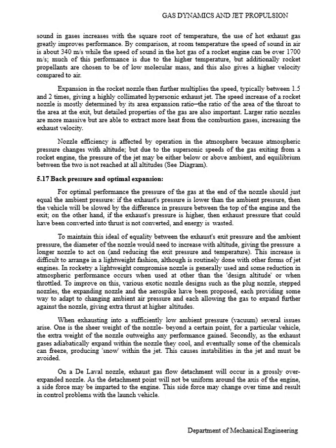To improve on this, various exotic nozzle designs such as the pulse nozzle, stepped nozzle, expanding nozzle, and the aerospike have been proposed, each providing some way to adapt to changing ambient air pressure and each allowing the gas to expand further against the nozzle, giving extra thrust at a higher altitude.